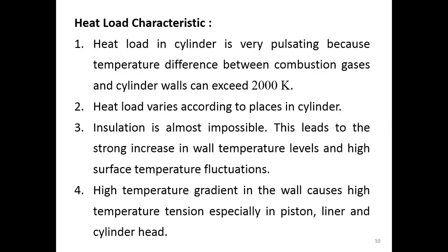Since we deal a lot with heat transfer, we know how heat transfer impacts our engines. That forces us to study heat transfer, and to study heat transfer, we need to know the heat load characteristics. This is very important. We need to know how our heat load behaves. The first thing we know is that the heat load in the cylinder is very pulsating. That means it's always fluctuating. It's never steady, always up and down, up and down.